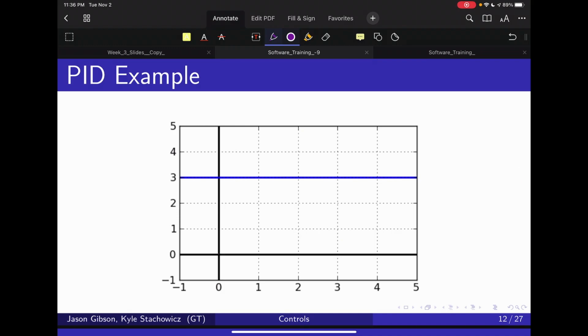So if we're doing the exact same thing we had before, which had a car going up a hill trying to reach 70 miles an hour, this is our target set point. When you're tuning PID, what you'll want to see is some proportional term such that you overshoot a little bit or get very close to your set point, some d so that your peaks are not too high, and then some integral such that your steady state error is very close to 0. Now, balancing these three terms can be very difficult and often just comes down to the application that you're doing.